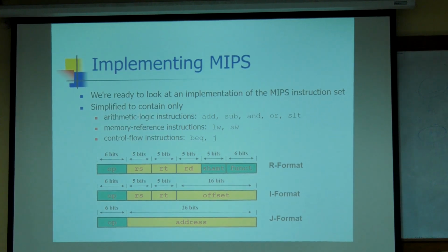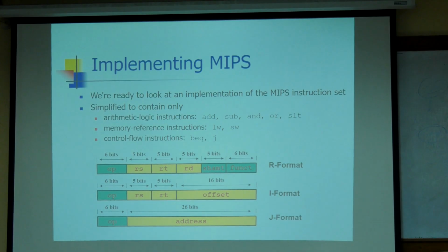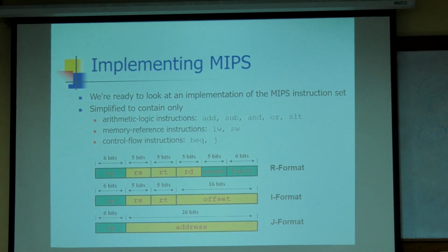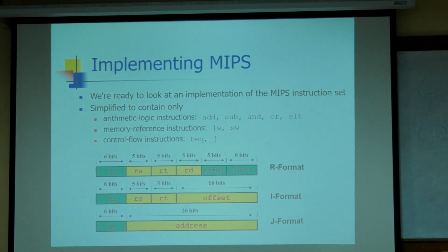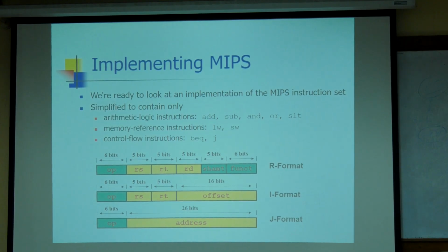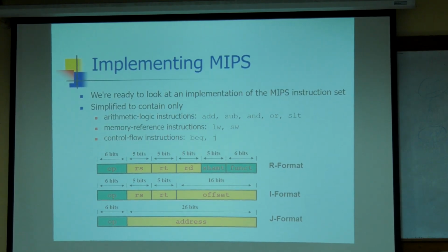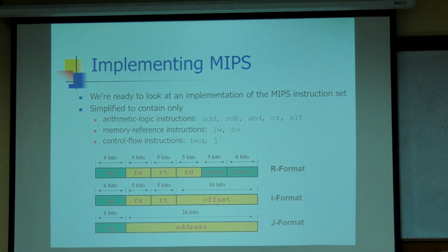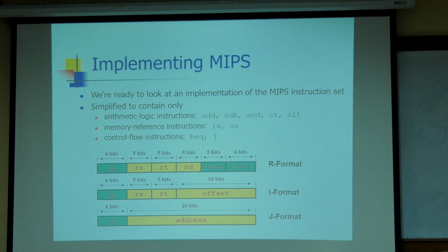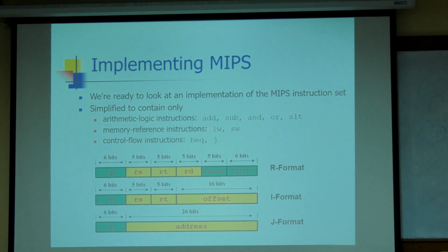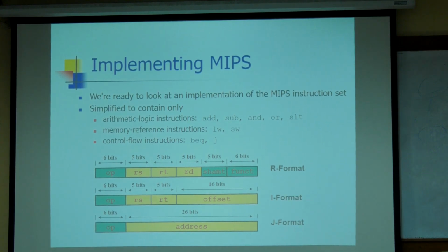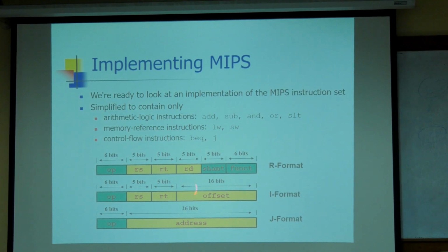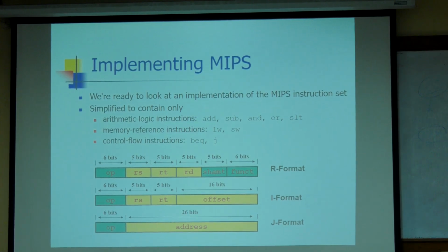So in this architecture, there are internal registers. Programmable registers, 32 registers are present inside the architecture. These 32 registers we can use for temporary storage. When the program is executing, it will store the temporary data, or the partial results, in these registers. Those registers we can use as source operands, and we can store the destination operand, the partial results, in these registers.